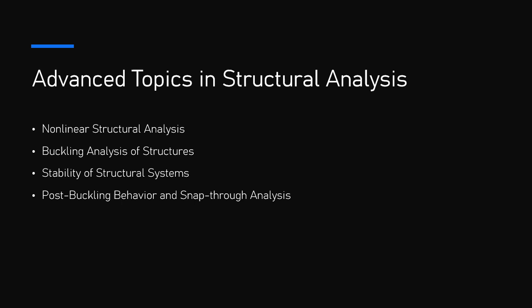2. Load step analysis. Static load increment. The load is applied in increments, and after each increment, the structure's response is updated. This is done until the final load is reached, or until the structure undergoes significant nonlinear behavior. Dynamic time history analysis. When the load changes over time, like in seismic or impact loading, dynamic analysis methods such as time history analysis are used. Nonlinear time history analysis considers both the transient nature of the loading and the nonlinear behavior of the structure.